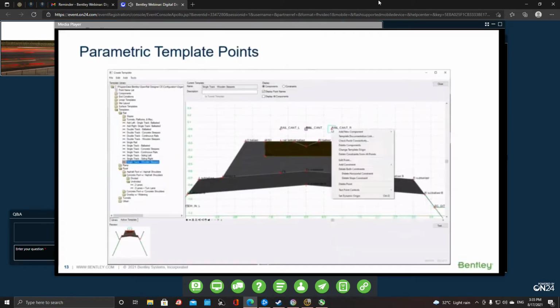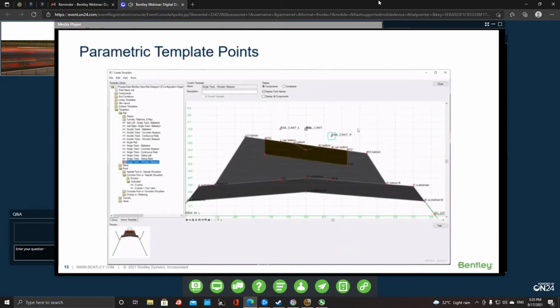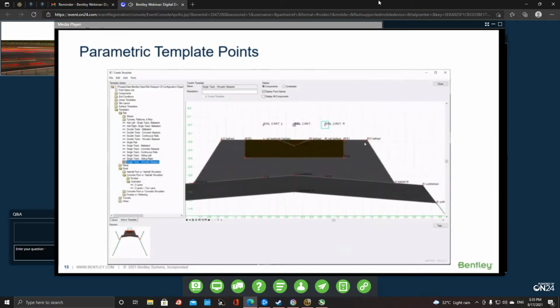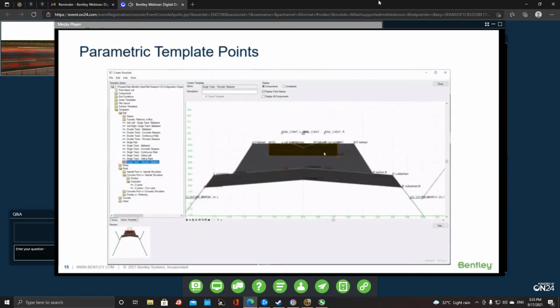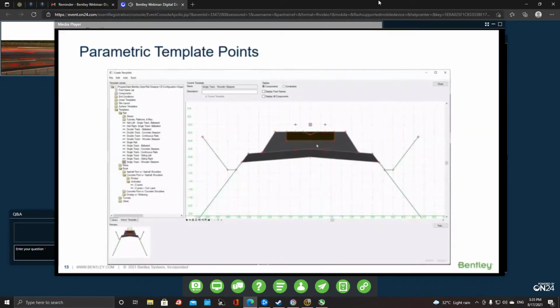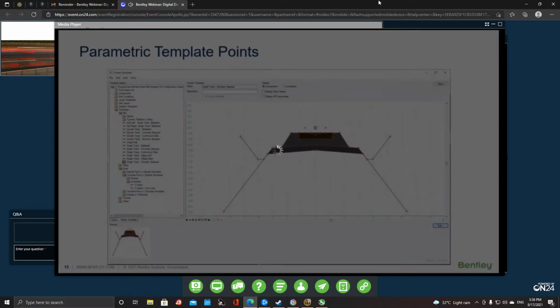Since this is rail, you put in points on the left or right side that represent the top of rail, the inner or outermost edge of the rail itself. From there you can simulate the behavior of the super elevation, and you can already test it out in the interface so that you would know more or less how the cant or super elevation would behave.